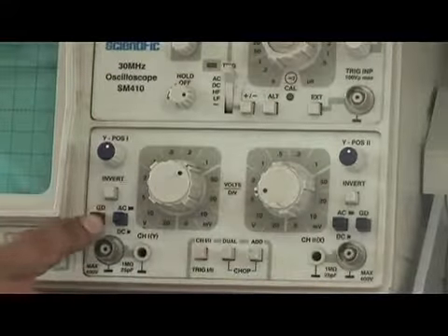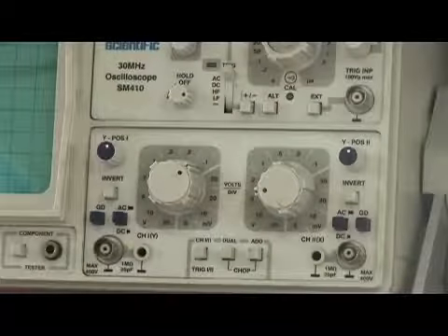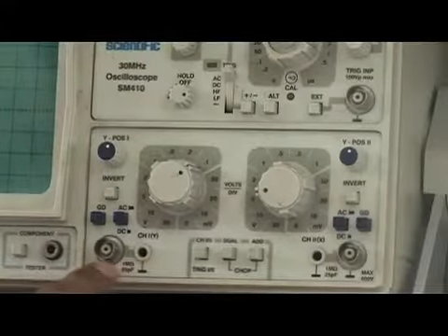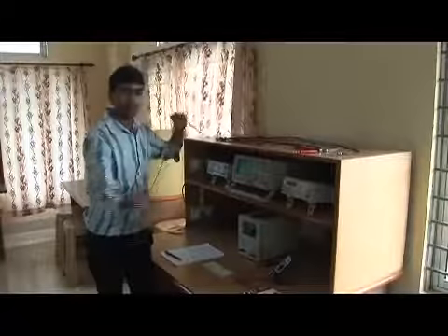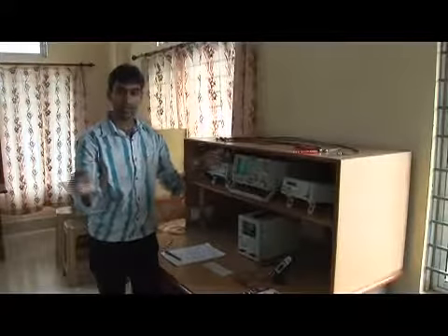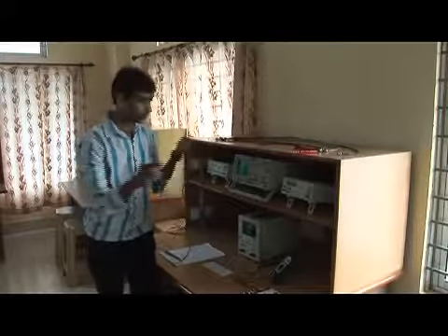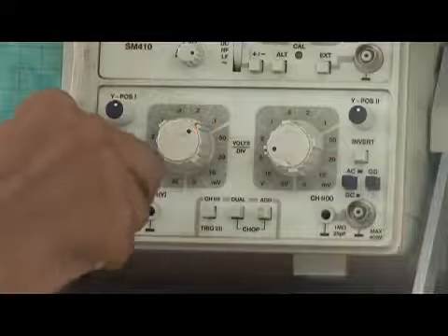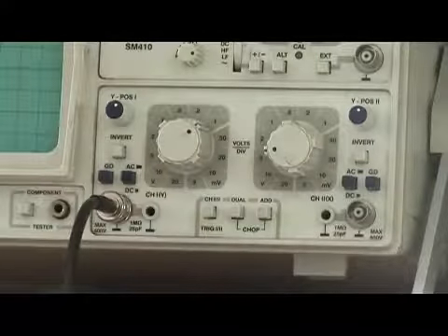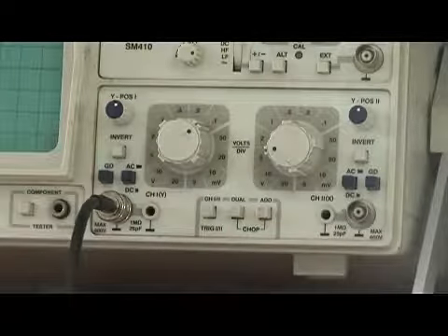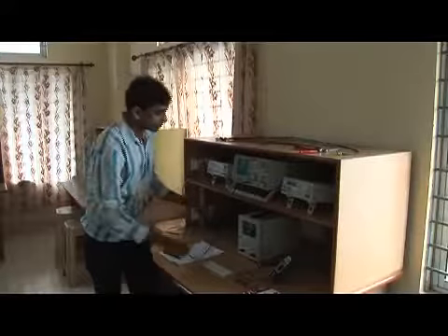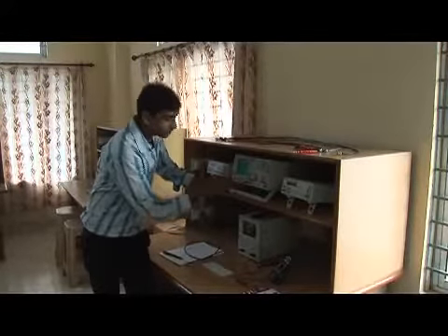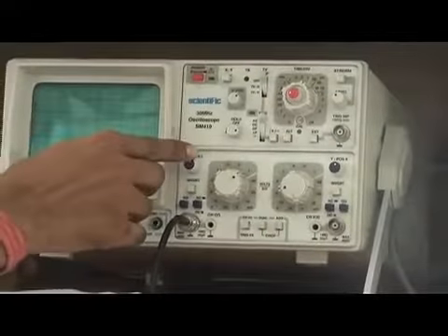If you look into it, there are various buttons over here, and one is known as the input. This is where we use a BNC both-side cable, which is known as a CRO cable. We use this connector over here in connecting this input. Now when it is connected to the input, whatever is coming in this side will be shown on the screen. So let us begin with the other things, like what is ground, what is AC, DC, what is this invert, what is this Y pos.